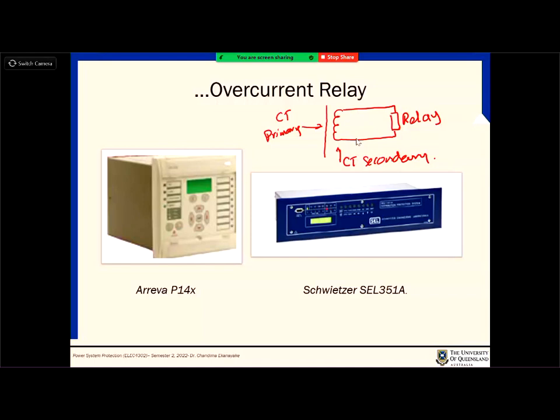Now when you can't push the current, then what happens? The system tries to develop the voltage to push the current. Okay, because at the end of the day, it's the dφ/dt. Now the flux changes, it's not opposed, therefore voltage suddenly builds up. So what happens is that if you keep a CT's terminals open, then there will be a very large voltage appearing across it.